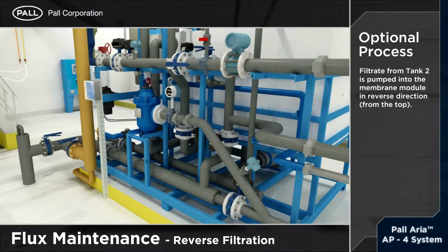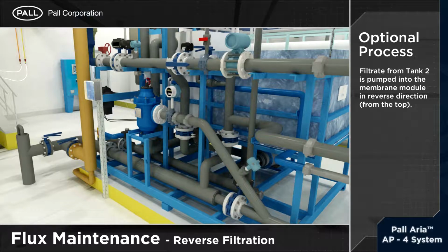As an optional process in the flux maintenance, a reverse filtration flush can be performed instead of a feed flush, depending on raw water quality.